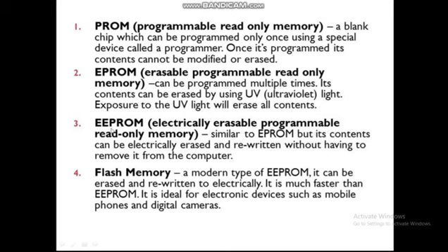Now coming to E-square PROM or electrically erasable PROMs. They are also called electrically alterable ROM, that is EA-ROM. They need not be removed from the motherboard as with the EPROMs, and they are byte erasable. That is, we can selectively erase the contents, which is very useful. Its contents can be erased and programmed in the system board itself, byte by byte.